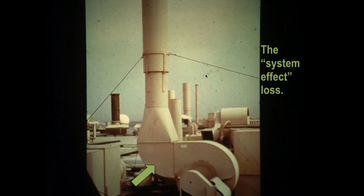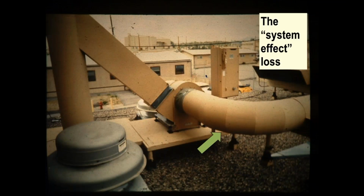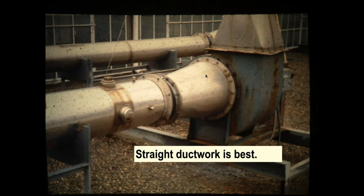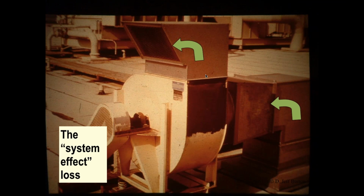So system effect losses, see it's turning right there. Here's the discharge here on the fan, right? Big 90-degree turn right there. That introduces a lot of loss. The losses there could be as much as 30, 40, 50% at that point. Okay, so that's why you want to avoid that. Here's another one. This is a classic, right? It's going straight on the discharge, but it's turning just before the suction. Again, another one. And the reason why I have so many pictures of these is it happens all the time, right?